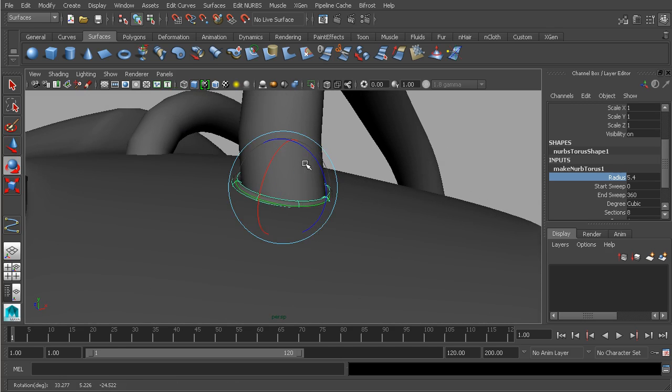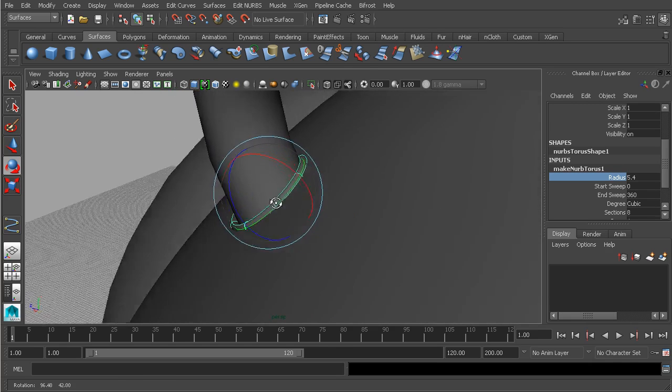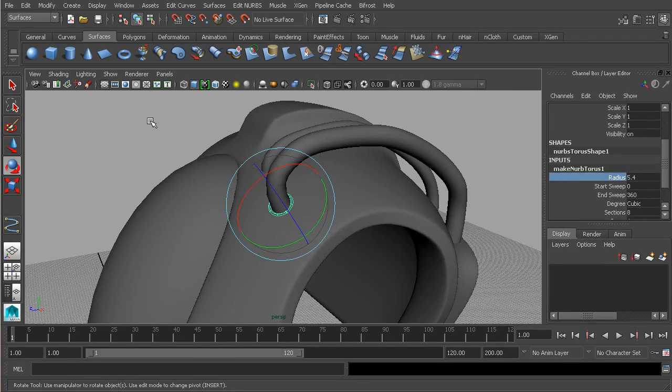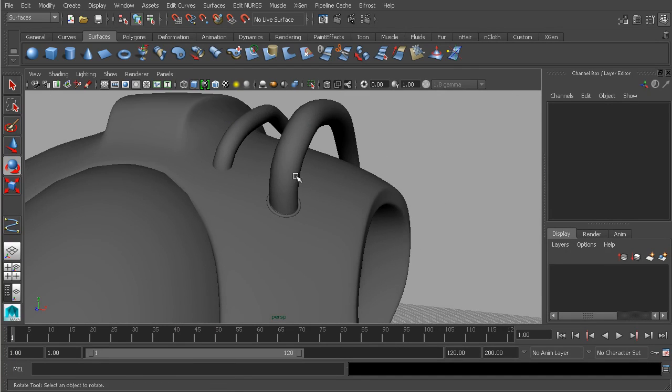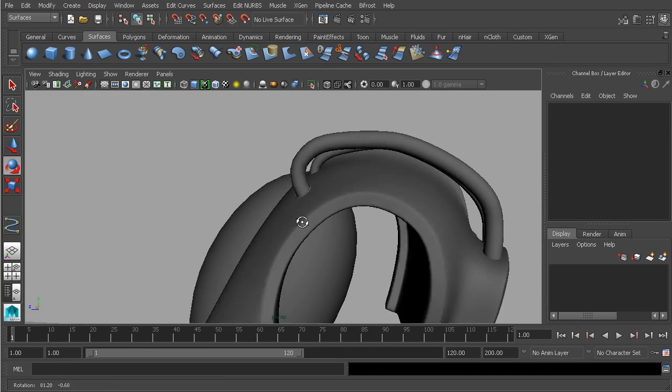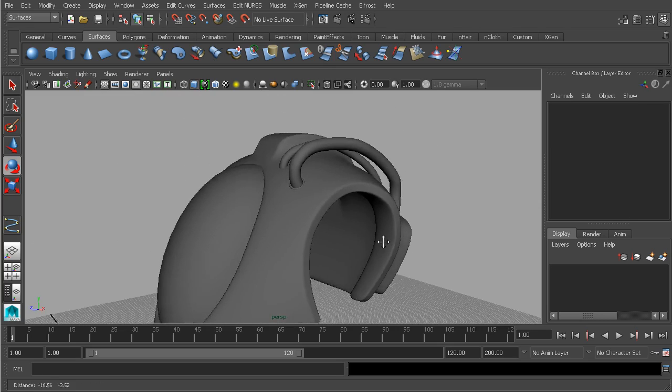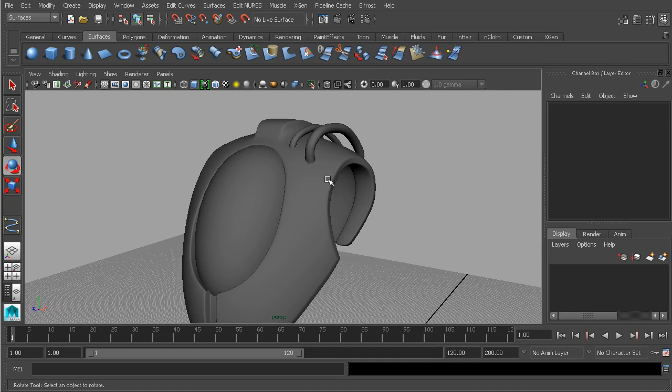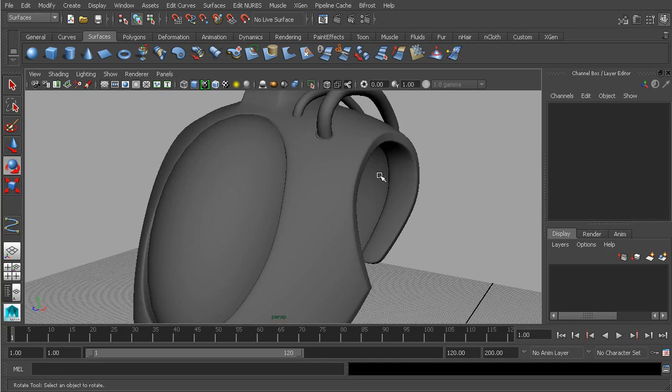And you can see now why I wanted this to come in at not too shallow of an angle. Even though it's hard to see, it really adds a lot when you have those visual seals and details on, so it doesn't look like it's just penetrating right into a piece of geometry. So have some fun with drawing out some curves. Use some different profiles to create the shapes. In this case, we just used a circle to create a tube shape, and then went in and added some seals to that.